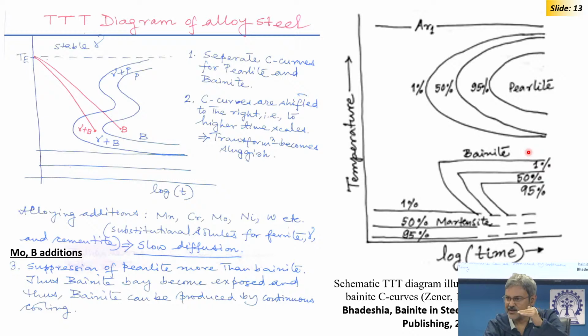So, first what happens is displacive transformation, which forms the bainite platelet supersaturated with carbon, and then the carbon gets rejected. If there is time, the carbon would end up at the boundary in the austenite at the boundary of the platelet, which is called upper bainite. If time is not there, the carbon will precipitate inside the bainite plate itself, which is called lower bainite.